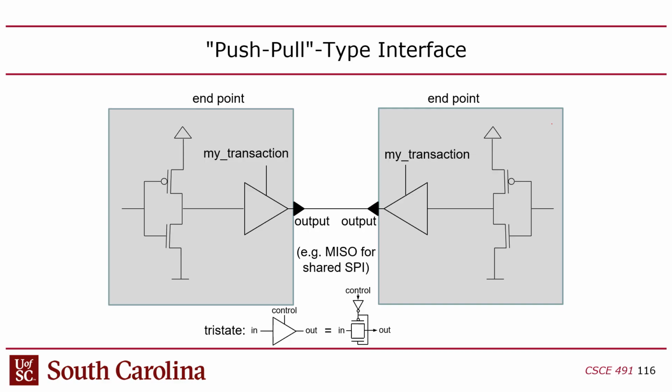We've talked about this a little bit, but you've probably noticed already that in the ESP32, the I/O pins are quite flexible, quite powerful. They support this tri-state buffering. In fact, the pins are all bidirectional. They can be set up as inputs or outputs. And so obviously there's a way to disengage, right? There's a way to basically cut these guys off if you don't want them on there.